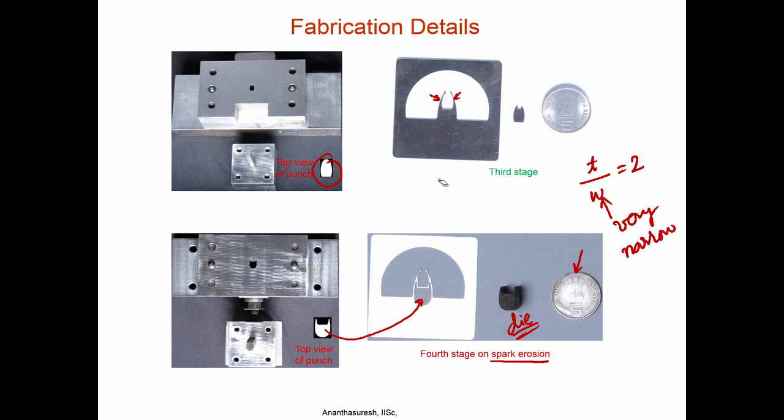The advantage of a batch production such as punching is that even if the size of the lot that you want to make is only 50 or 100, it is economically justifiable, whereas lithography will not be justifiable. And the whole die set that we made for this application was not exceeding 30,000. Okay. So, it is possible to adapt existing processes for making compliant mechanisms.